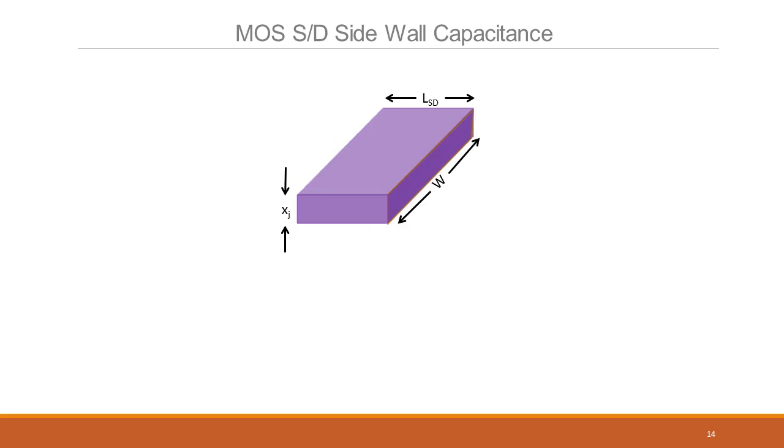Okay. What about this capacitance? This capacitance actually is incorporated in the MOS transistor itself. Okay, and it's not considered separately because this face actually touches the channel. The channel capacitance, the CGB, CGS is there. That it gets accounted there itself as part of the MOS transistor itself. So its capacitance is definitely there.